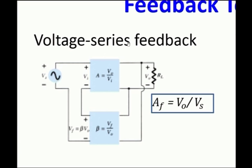If it is shunt, there must be a current source, and the output signal will be connected in parallel to the input current source in that case. So, now we are looking at voltage series feedback, for which the gain of the circuit is V0 by Vs. This is V0, the output voltage, and this is Vs, the input voltage. We know that the voltage series feedback is a voltage amplifier, and the amplification factor is the output voltage by the input voltage.